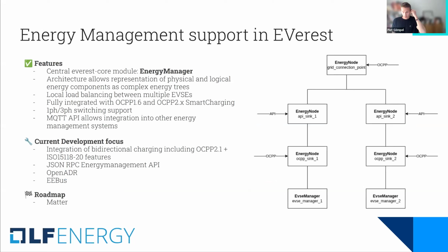Zooming in a little bit on the energy management support in EVerest, there's one central module in EVerest that is responsible for that. That's called the Energy Manager. It has a very flexible architecture that allows to represent basically arbitrary physical and logical energy components as a complex tree structure. So you can really design your grid connection fuses and fuses of your charging stations and define where you want to have external inputs.